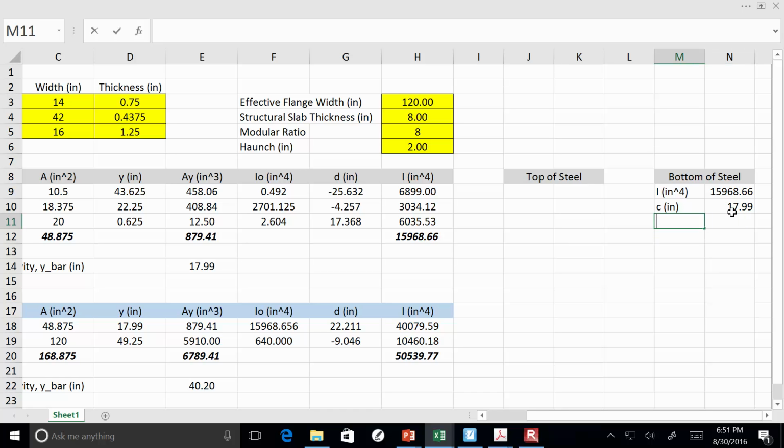So our section modulus, which is going to be in inches cubed, right? If I take inches to the fourth, I divide it by inches, that's going to give me inches cubed, is just that divided by that. So it comes out to be like 887 point something. And that's a really useful property if we're trying to determine bending stresses. Because if I've got a moment, and all I do is just divide by that, that'll tell me the maximum bending stress there on the bottom. That's pretty important when later on I might say, okay, let's calculate the bending stress on that bottom flange and let's see if that's an acceptable value. Maybe that stress needs to be less than the yield stress or what have you. So I might calculate it and see if it's less than 50 KSI or what have you. All right. Sound good? Okay.